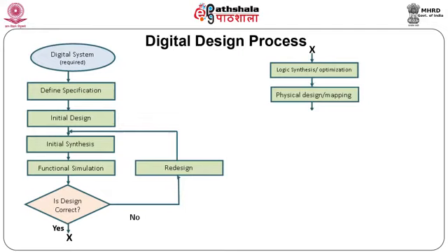Once the logic synthesis and optimization is done, the next obvious step is to design the logic circuit using available logic resources. The physical design performs the 2 basic operations: placement and routing. Placement of the logic functions in the optimized circuit in the target IC, and interconnecting the components in the chip, which is popularly known as routing.